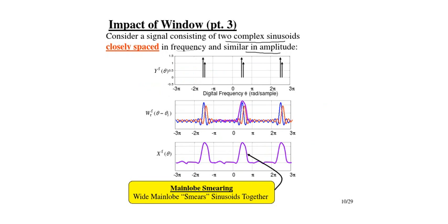So when we shift the DTFT of your window at theta 1 and theta 2, theta 1 will be your blue color curve, and when you shift it at theta 2, this shows you the next curve. So when you see here, since they are very closely spaced, the resultant function, which is the DTFT of your finite duration signal, looks like this, right?